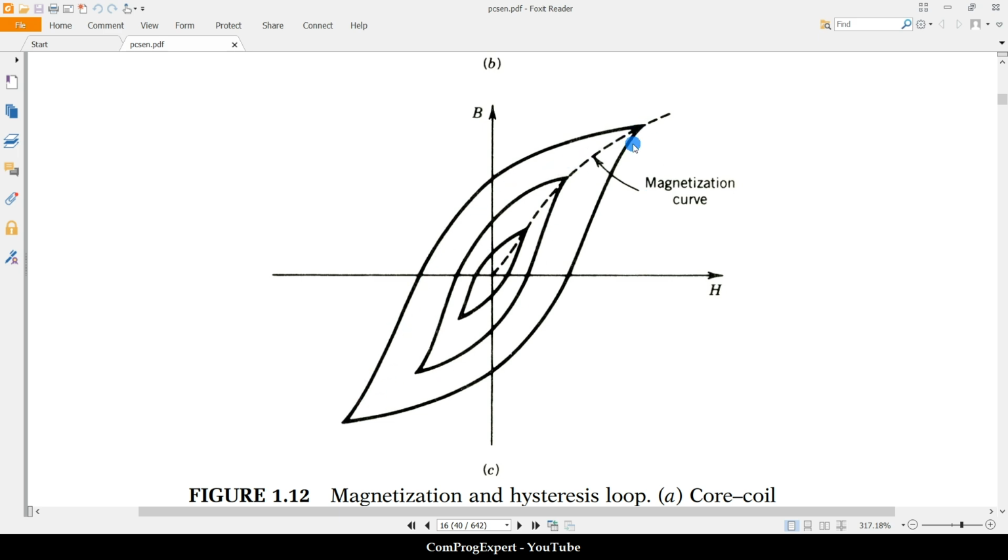For example, for permanent magnets, we need to consider the hysteresis loop for the finite element calculations. Later I will show, because in that case the area of the hysteresis loop is high and we need to do the calculations considering the hysteresis loop. But for the soft iron, for faster simulations, we consider the normal magnetization curve.